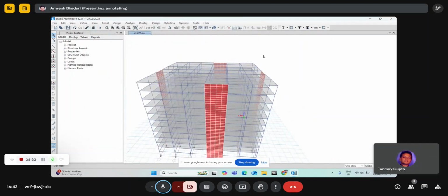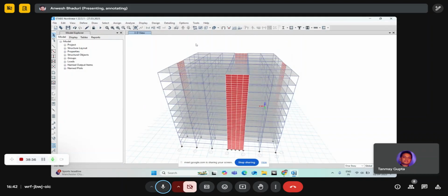And your steel design is also the same, only the modeling is similar to your concrete, like RCC. Only the definition part is different. After finalizing the geometry, your connections need to be defined. If it is a fully moment release connection, we need to go and assign releases. If it's semi-rigid, then as per the joint stiffness, we need to assign partial flexibilities, right?